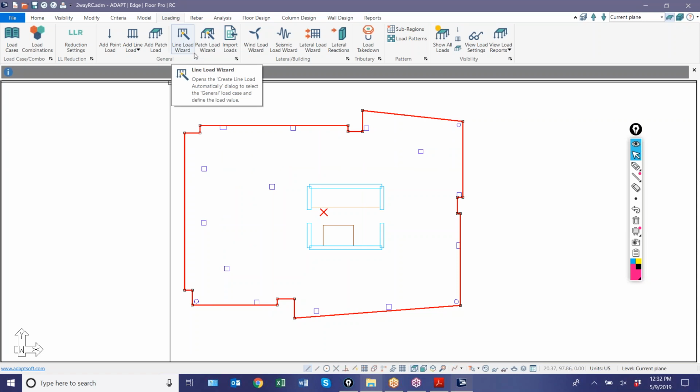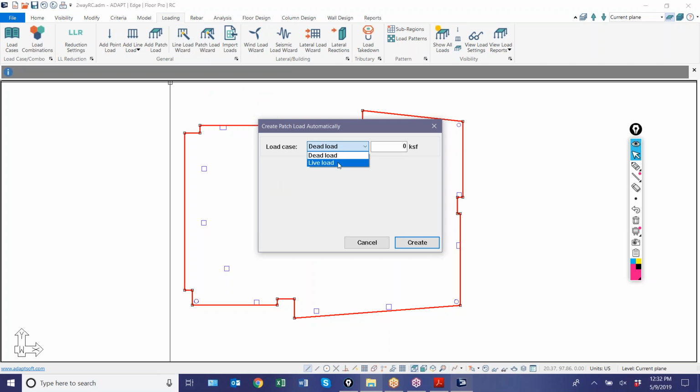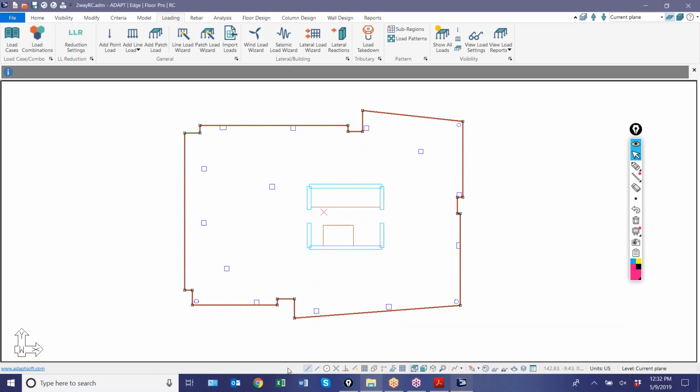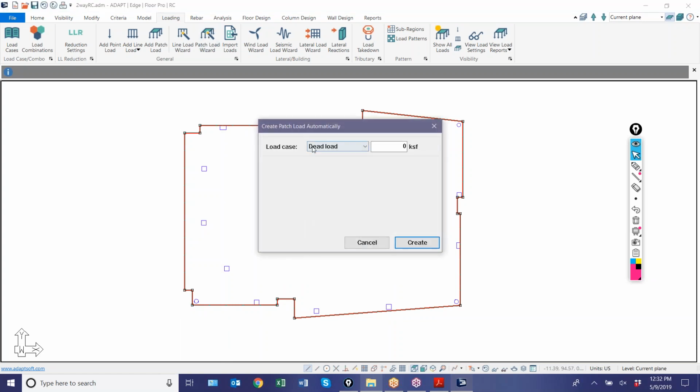We're going to assume that the loads are 50 PSF unreducible live load plus 15 partition. So I'll add a patch load live. I'm going to add partition here, so it'll be 0.065, and that's going to map load to this selected slab. Loading is always cumulative. So if I went and added a -20 live load to the slab, then the net effect would be 45 PSF live load. So the loading in the program is always cumulative.